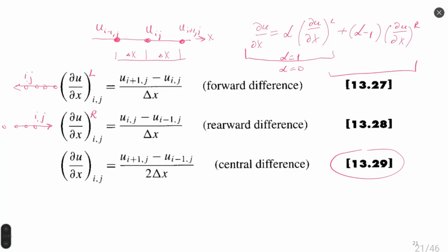These three equations are not the only options which we might have to approximate our derivatives in terms of points, to transform a differential equation to an algebraic equation. There is a huge number of such relations which you might find, for example, in Anderson-Pletcher-Tannehill, which I recently suggested you study together with CFD methods.